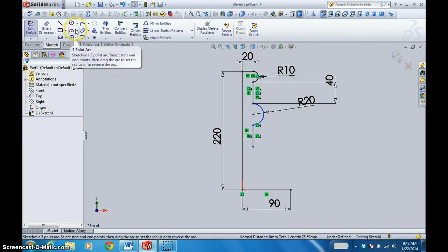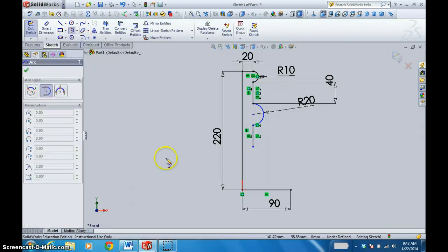We'll jump back up, and we're going to draw a tangent line, or tangent arc, sorry. So grab the tangent arc, grab our lower point, and we're going to get an angle of about 90 and a radius of about 60. We can draw it out a little bit here, keeping that at about 90. Whenever you get close, click, and then we'll create a final tangent arc to connect to our bottom point, and click for now.